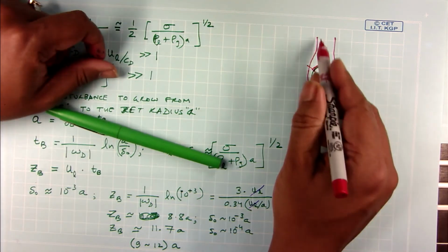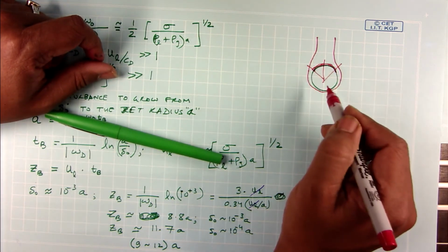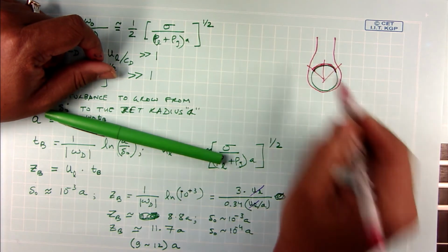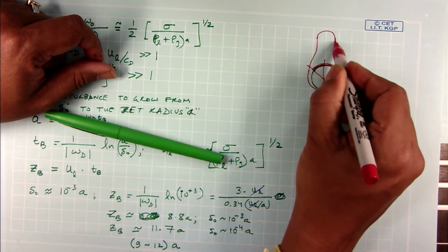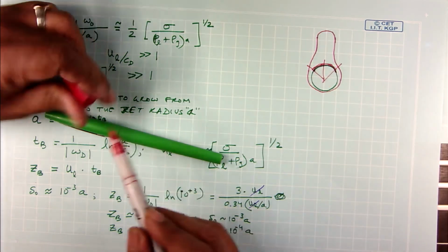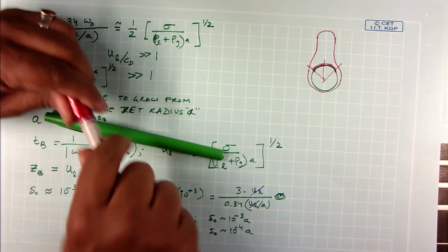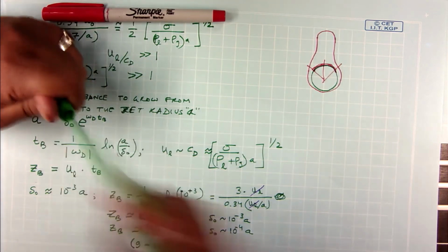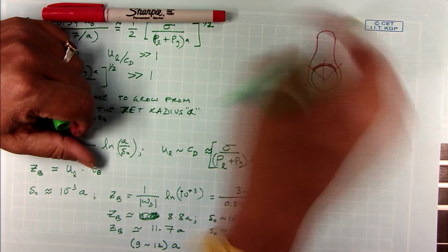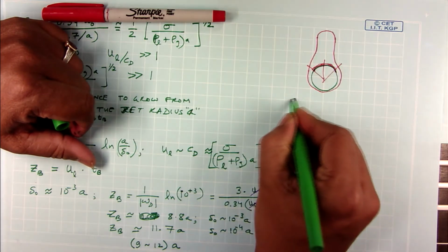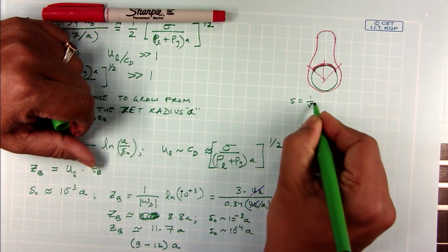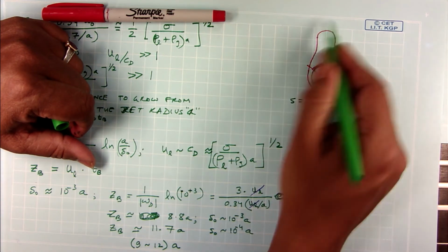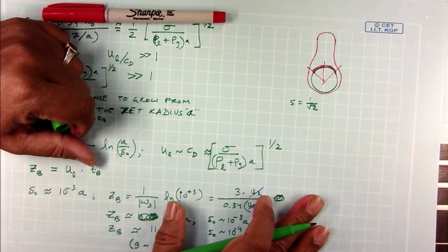Just like you have the boundary layer profile around a hot cylinder, in film boiling also the vapor film looks something like this, very similar. That is how the vapor bubble looks in film boiling. The value of S that corresponds to a shape like this, if you do a best fit, is S equal to 1 by root 2. If I substitute S equal to 1 by root 2 in my Bessel's function solution, I get a shape that looks like this, very similar to a film boiling bubble shape.